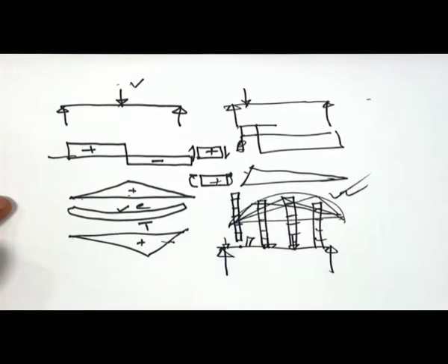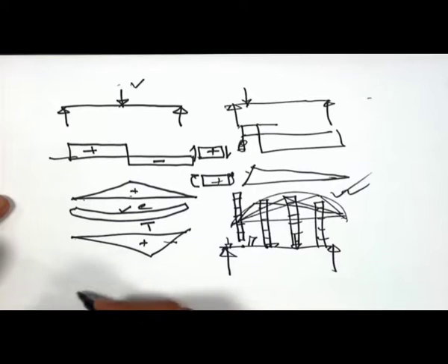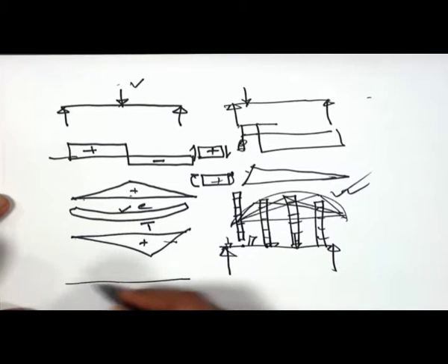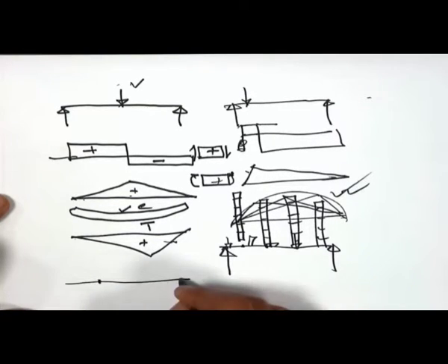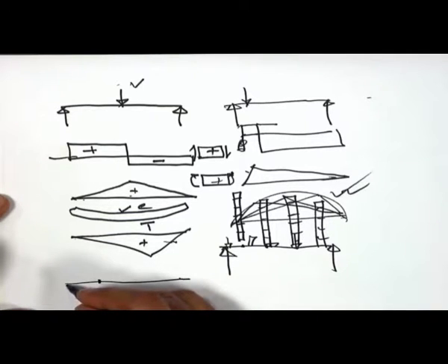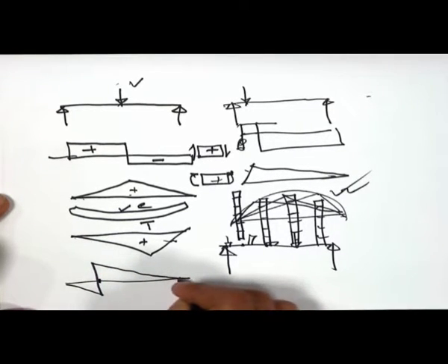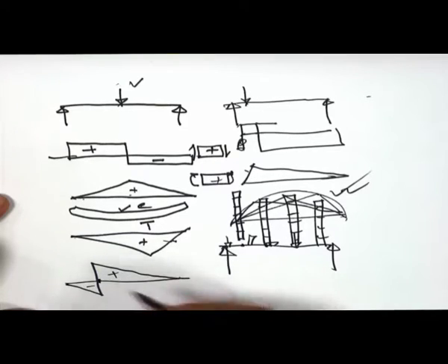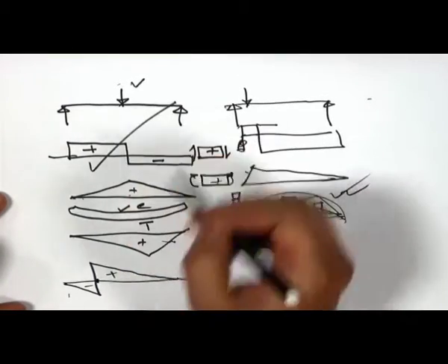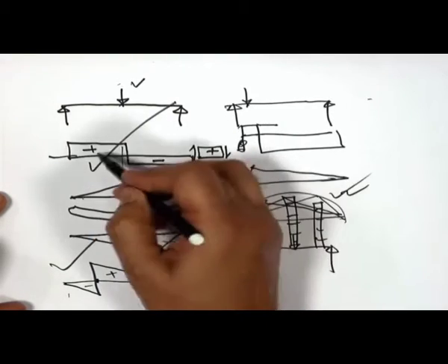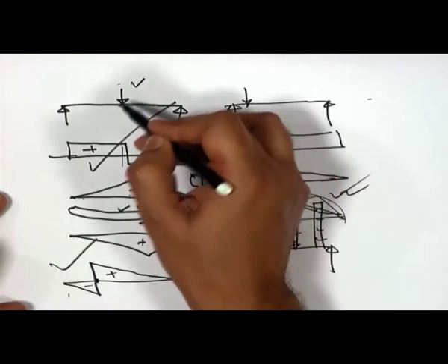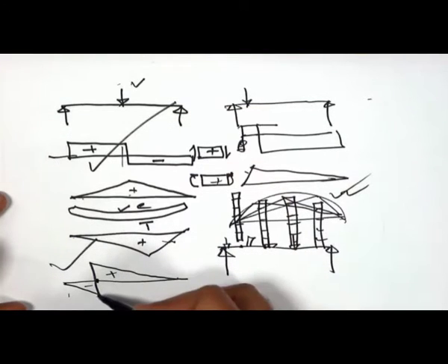So, is it not better that I select a location where I am interested in determining the variation, suppose the shear force, and then as the load moves over it, I plot along the length the influence line, the variation of the shear force. So, now this is the shear force diagram of the same beam with a constant position of the load, and this is the influence line diagram.